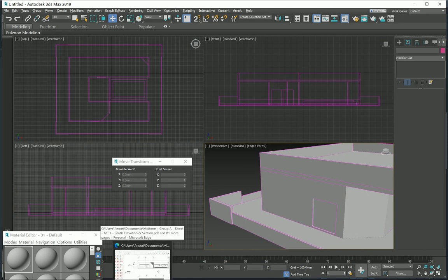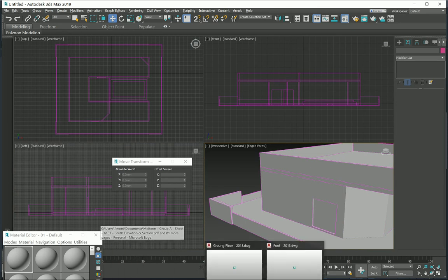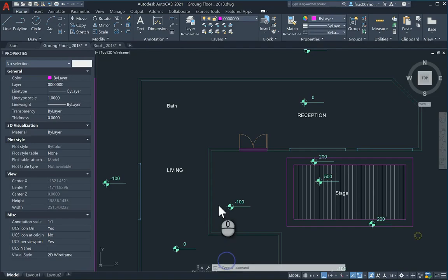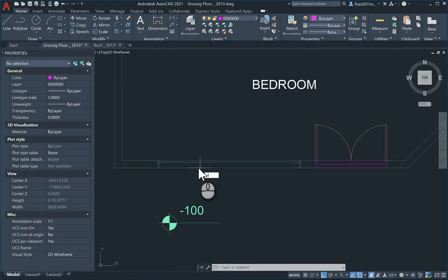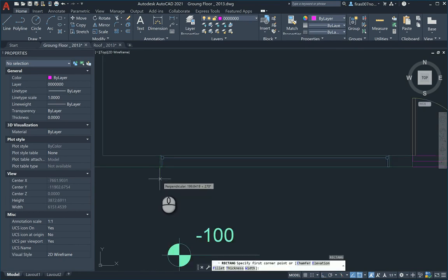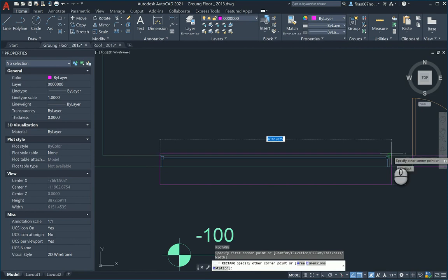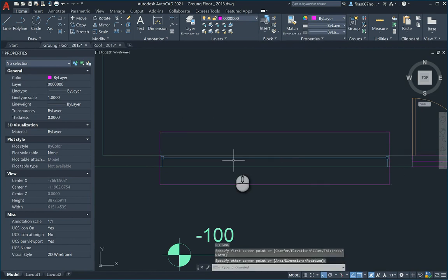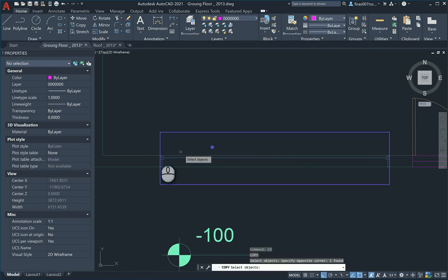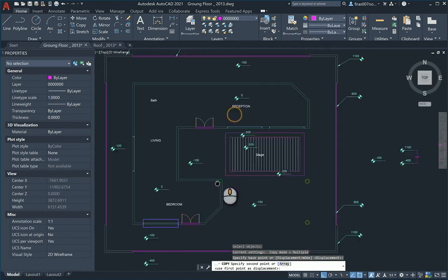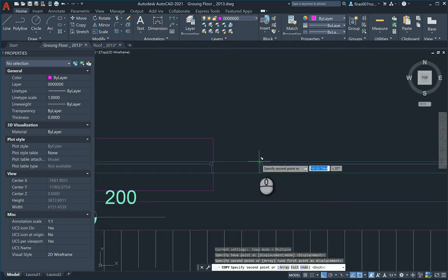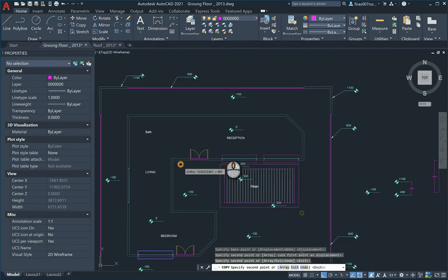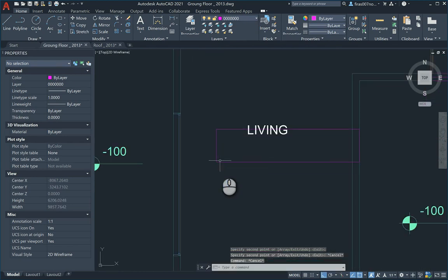All right, so okay, where are we? AutoCAD, the windows. So again, I'm going to use a polyline. I can use the rectangle with the tracking tool again. Just put the mouse here and then move my hand, put the mouse here without clicking, push my hand up. A faster way, or the easy way, use the polyline. Okay, that's one here, and that's one here, and I'll just place one here randomly and then rotate it.